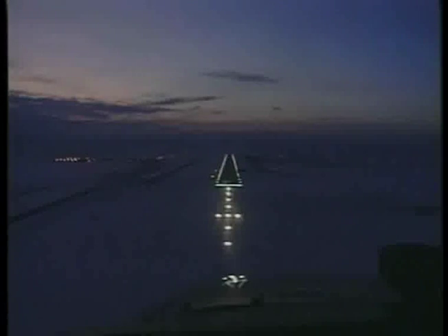To conclude your flight, the same landing procedures and techniques used during the day are also performed at night. However, runway lights, airport lights, city lights, and the airplane's landing light may create illusions not encountered during daylight. Thus, speed, altitude, and distances may be more difficult to judge.